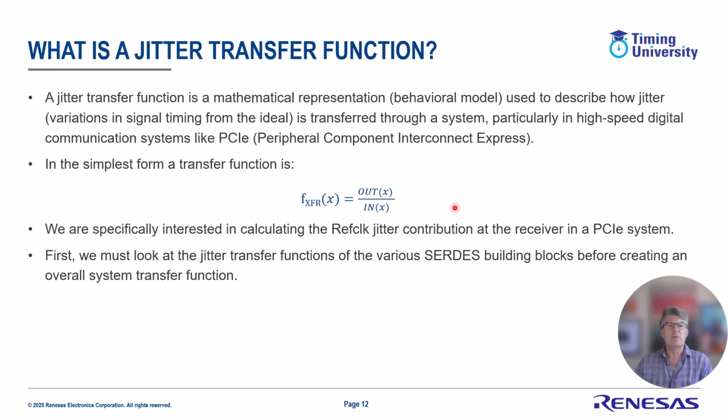In its simplest form, the transfer function of x is out x over in x, where in our case the input would be the reference clock phase jitter. So before we can make use of this, we need to look at the jitter transfer functions of the various SerDes building blocks before we create an overall system transfer function.